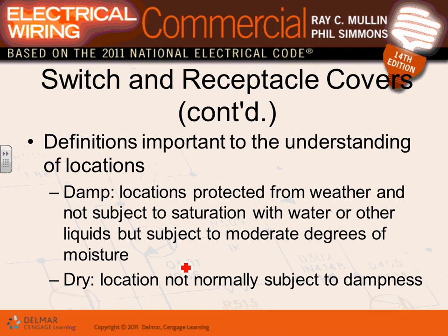So the most important in damp location too. So then becomes, guys, damp location, dry location, wet location becomes a big definition for them, because if you install a receptacle in damp or wet location, this receptacle has to be weather resistant.